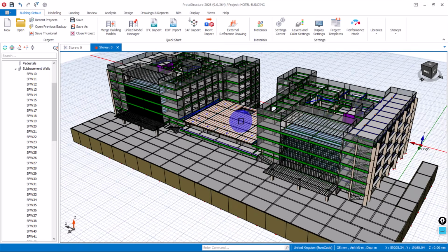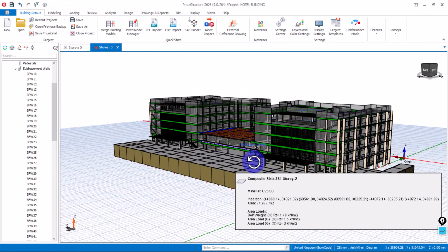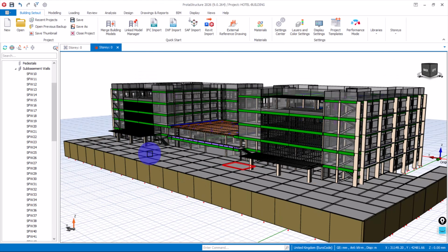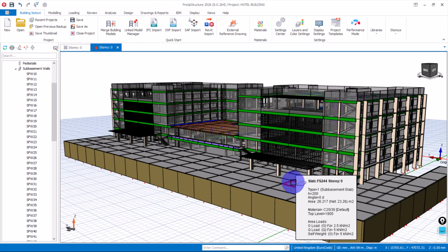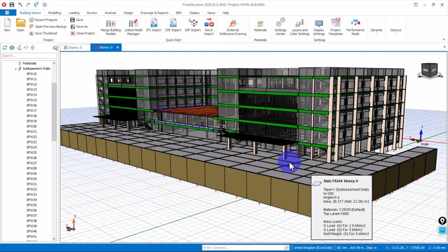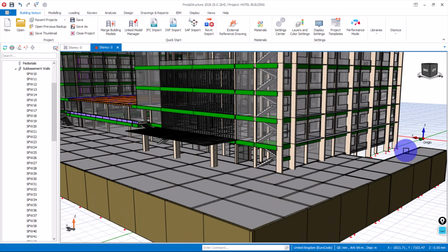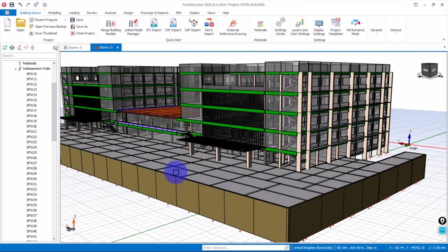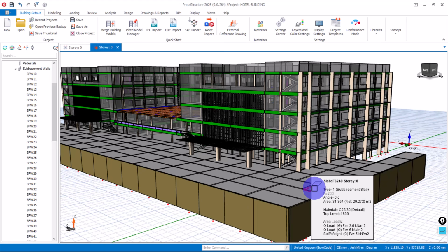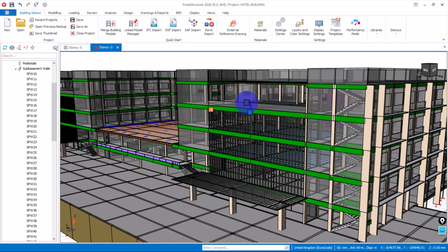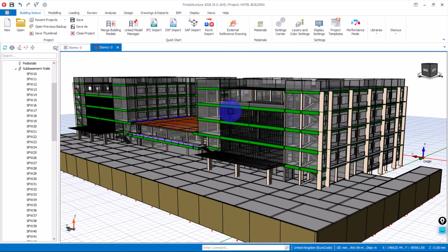Now in the next video, I'll be using the same building to show you how to exempt your basement walls and columns from wind load, because knowing that basement walls and columns are not meant to resist wind, most times you can choose to exempt them from your wind effect. I'll be showing you how to model that and then exempt your basement members, for example walls, columns and beams, from wind effects, and also from seismic effects for those that are in a seismic or earthquake region.